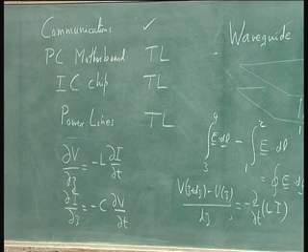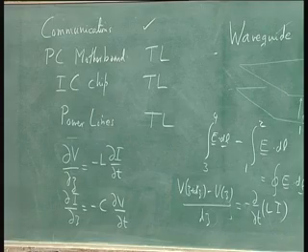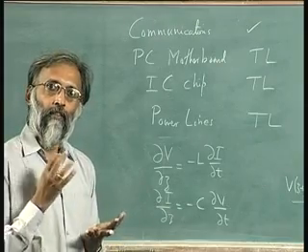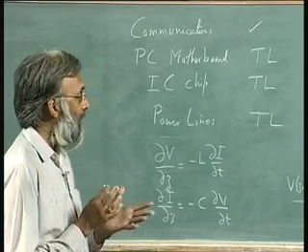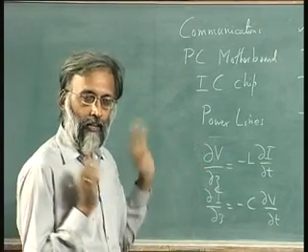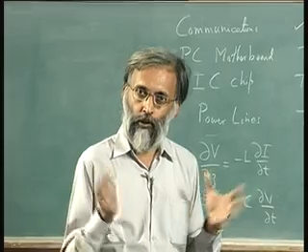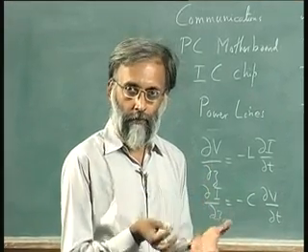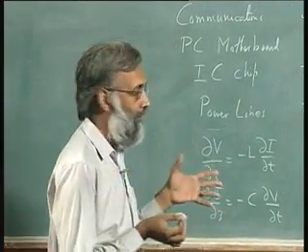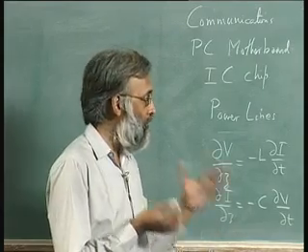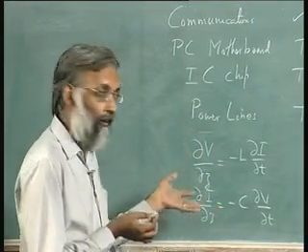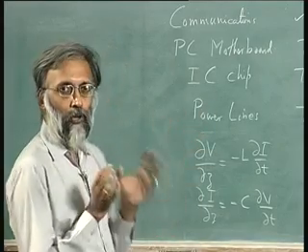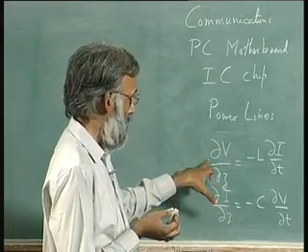The lesson to be learnt here is all the work that we have done in electromagnetic theory, statics, motional EMF, waves, has finally reached here. It allows us to define a wave that is bottled into a pipe. And that wave that is bottled into a pipe, a useful variant of that wave is what we call a TEM wave, and that TEM wave can be modeled by circuit concepts.